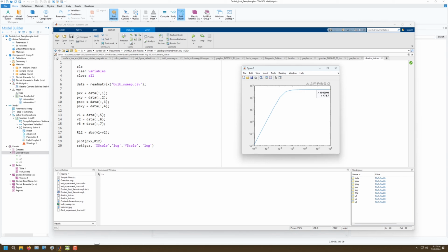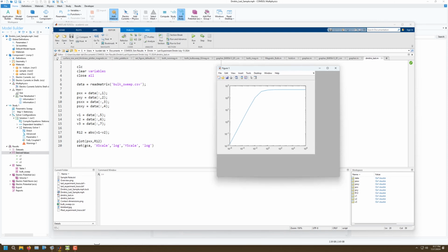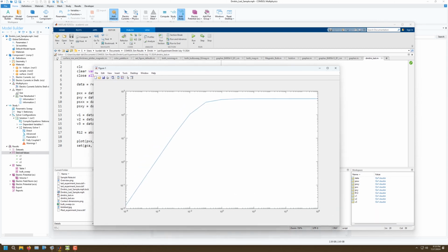Like, if we wanted to be really mean, we could just make Dimitri figure it all out from here. Because if he knows what the sheet resistivity is, 1 kiloohm I think I said it as, then he can just take this slope to get the geometric factor, and the ratio between 478 divided for 1 sheet resistance to get his thing.